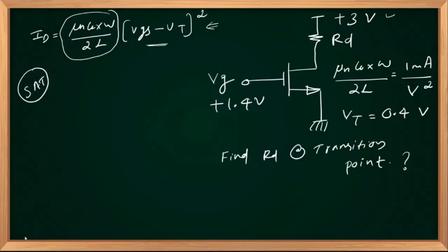Right. So what is VGS? And I should identify VDS, and that should be equal to VGS minus VT, right? There will be a drain current flowing through the circuit. It depends on the VGS minus VT difference squared multiplied by the constant. All constants are given to you. That current creates a drop across RD, ID multiplied by RD.